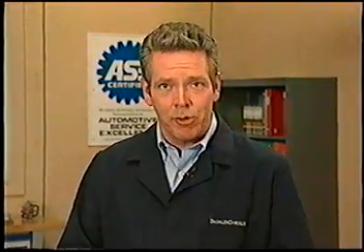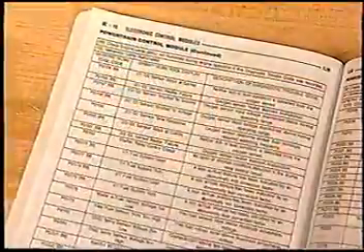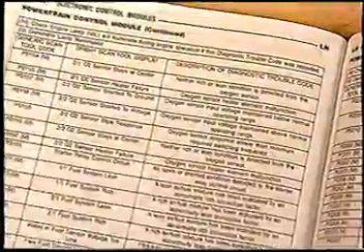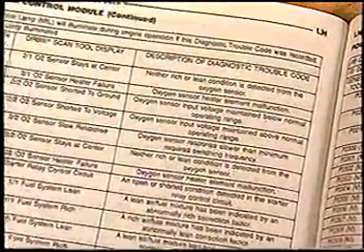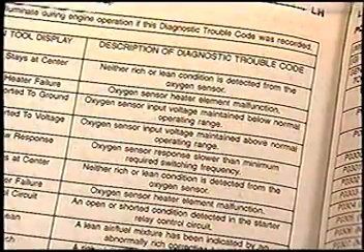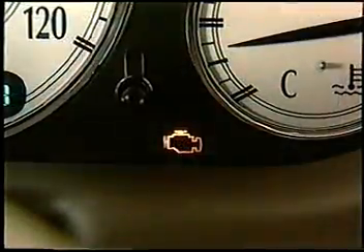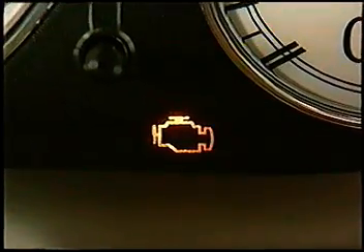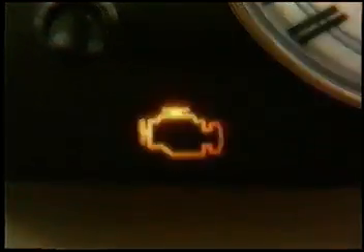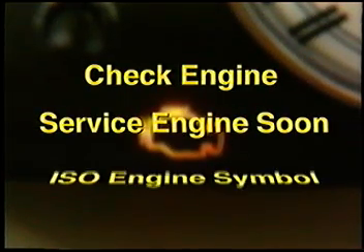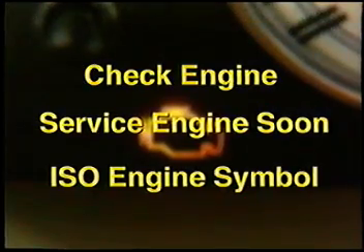You should know that these monitors detect faults by inference and not directly. If the PCM decides that trouble in a monitored circuit would result in a certain increase in emissions, a diagnostic trouble code, or DTC, is stored in the PCM's memory, and the driver is notified of a concern by the illumination of the malfunction indicator lamp, or MIL, which can be seen as either a check engine lamp, service engine soon lamp, or the ISO engine symbol.